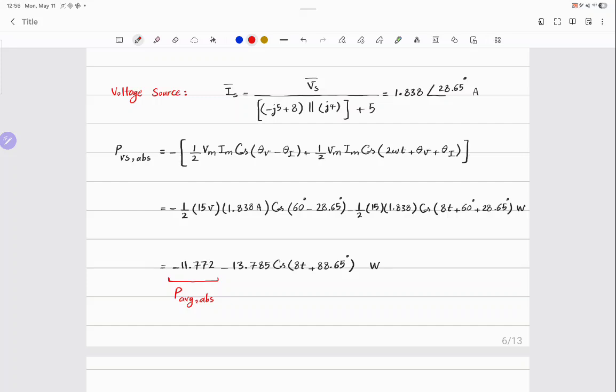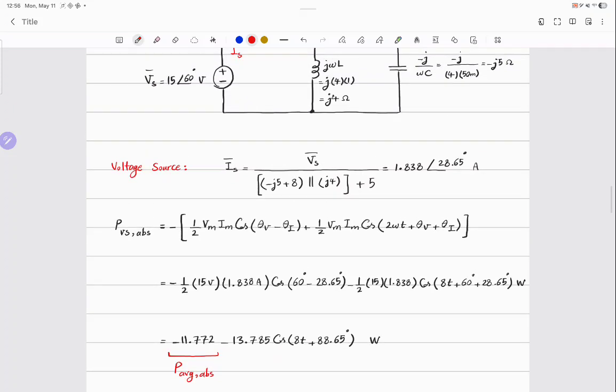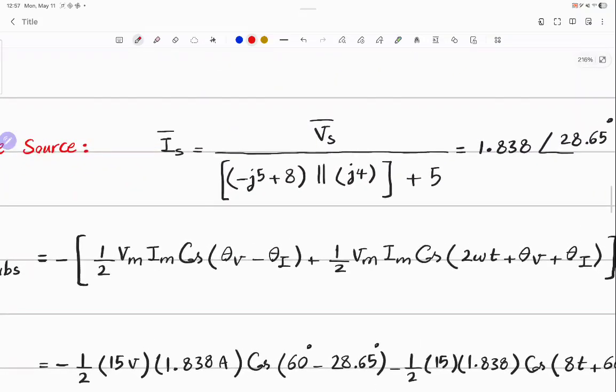Any problem with that first part? Now, Luke, can you answer this question? Why are we interested in finding the voltage and currents in polar form? So you can use it to find the power, all the other. Which parameters exactly need the voltage and current to be in polar form? Vm, Im, theta V, theta I, right? Do you see these in the equation? Vm and Im. Which one is easier to immediately write Vm and Im based on? The polar form, okay?